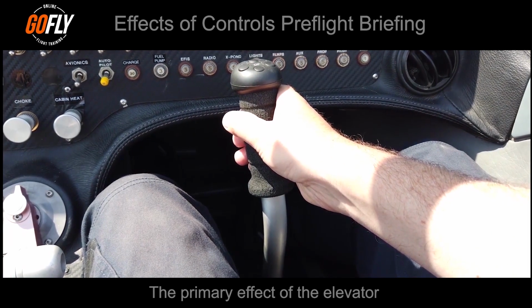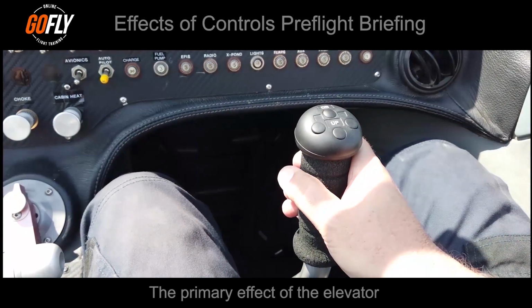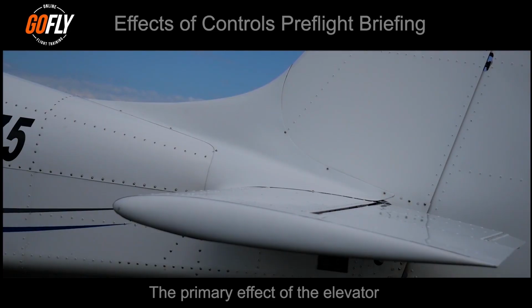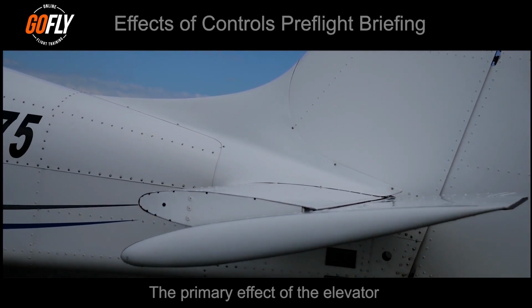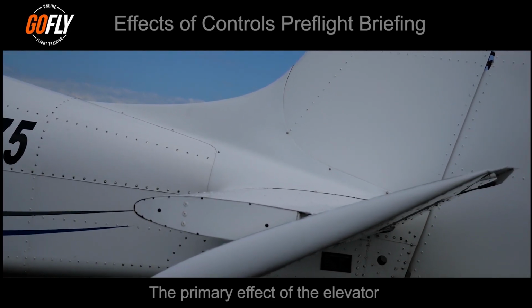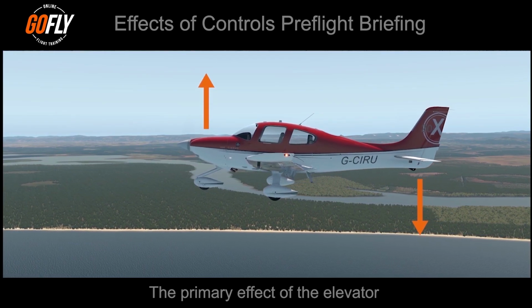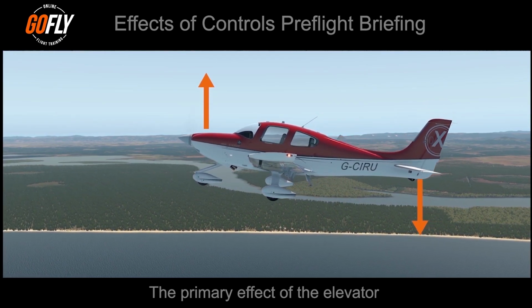The elevator is controlled by the forward and rearward movement of the yoke or control stick. When the control column is moved rearward, it deflects the elevator upwards. This deflection causes a downward force on the tail, which causes it to move down, which then causes the aircraft nose to pitch up in relation to the horizon.